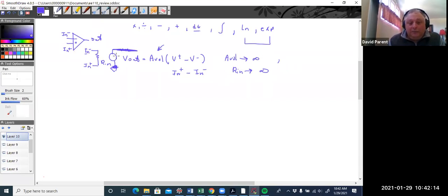Because it's a behavioral voltage source, rather than just some DC thing that is set, it depends on two node voltages. But it's still a voltage source and it's still ideal, meaning it can supply infinite current. That's not true in a real device, but if we keep the resistances of whatever it's driving large, it's effectively true.